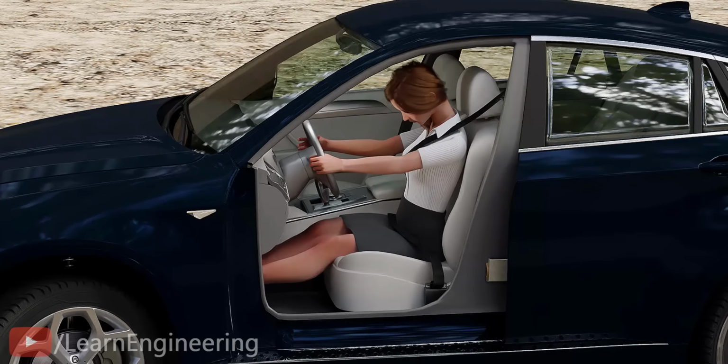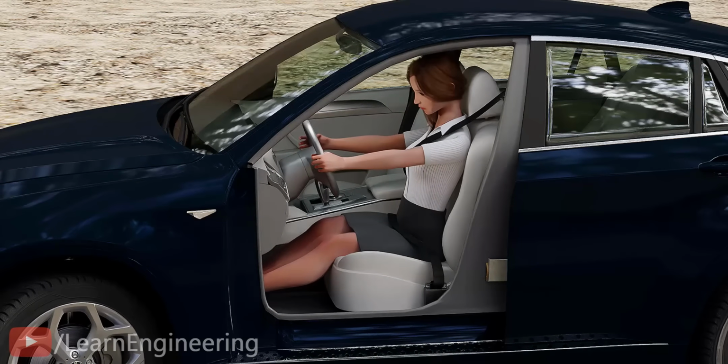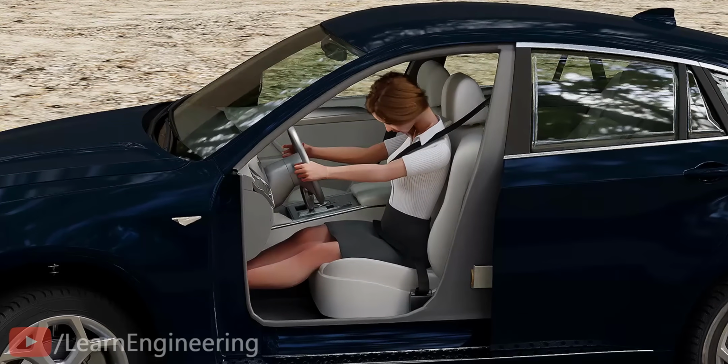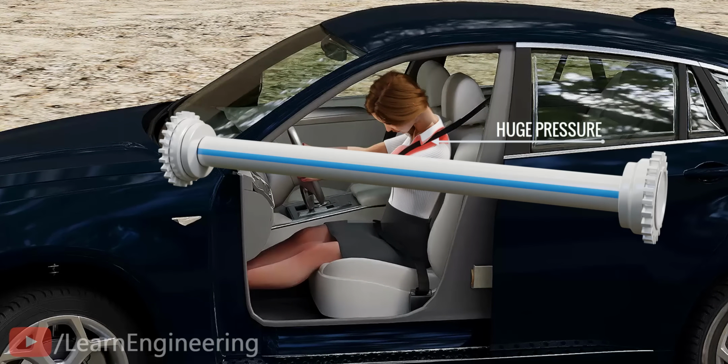completely during an accident, the belt will create tremendous pressure on the passenger's chest, which can lead to internal organ injury. This risk is why modern seatbelt retractors come with a torsion bar. The torsion bar helps to release the belt a little when it reaches a critical load, thus saving the passenger from excessive pressure on the chest. Let's see how it is done practically.